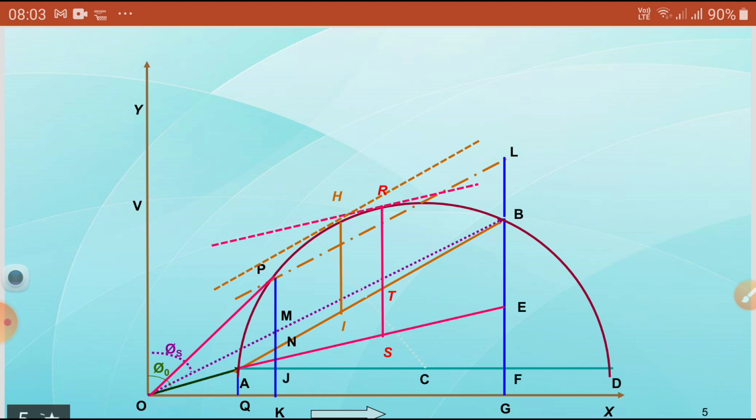At the same time, you can observe one thing also. While applying the load on the rotor in case of a synchronous motor, it will run at the same constant speed only, that is at synchronous speed only. But whereas in our induction motor, if we add some load, automatically the rotor will slowly reduce its speed.